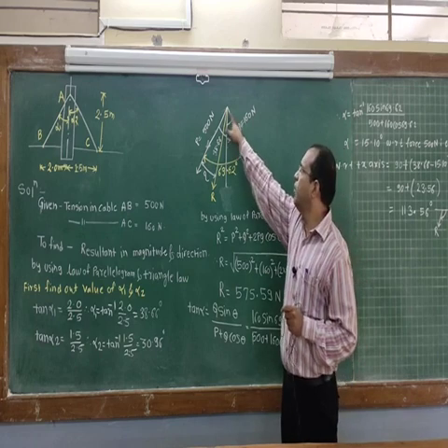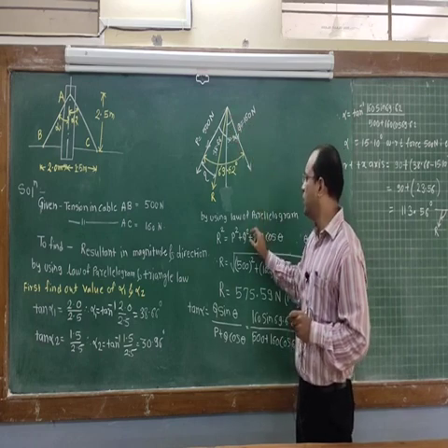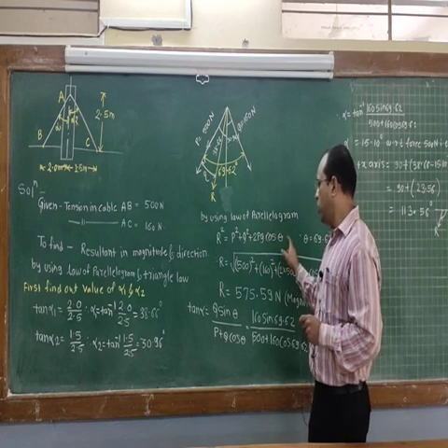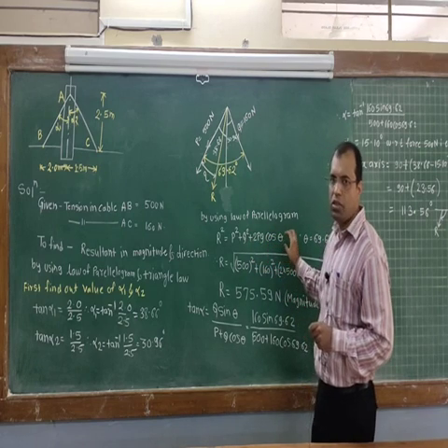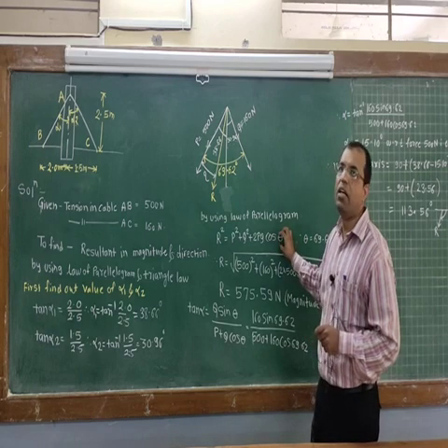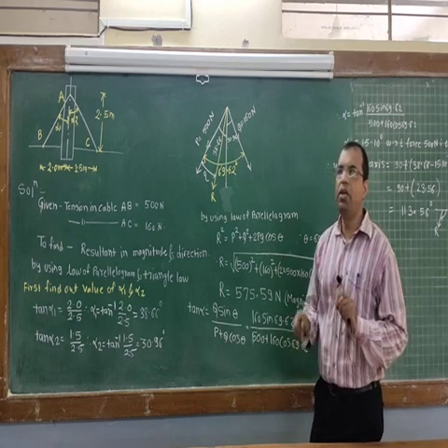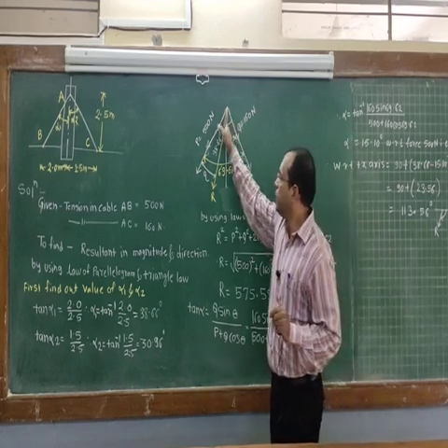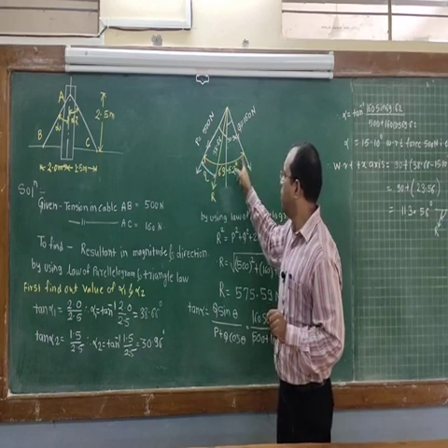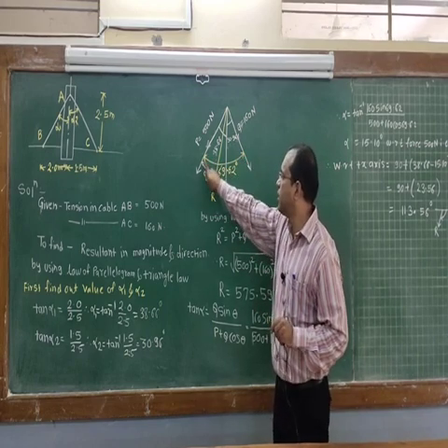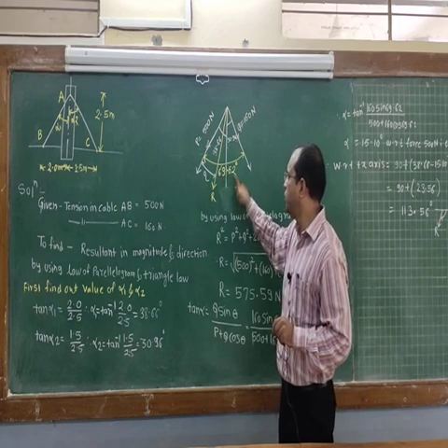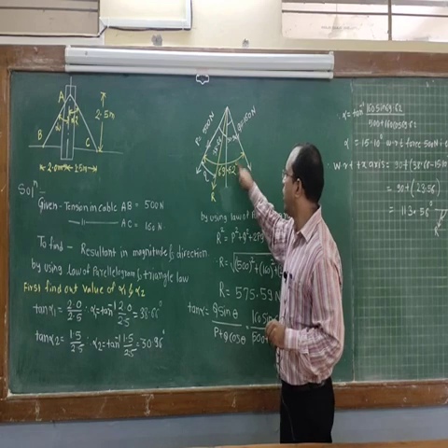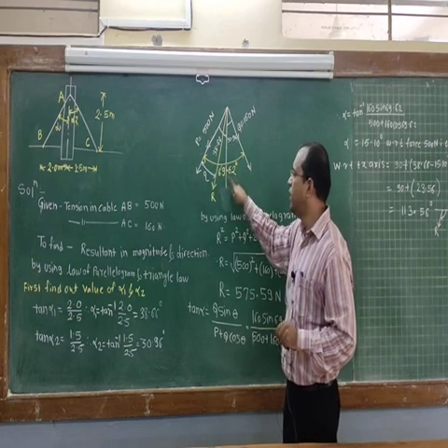Now the tension in the cable AC, let's say it is Q, that is 160 Newton, plus twice of PQ cos of theta. So please remember this theta. Many students make a mistake in that. Theta is the angle between the two cables or the two forces. So here theta is the angle made in between these two forces, the angle 69.62 between force P and force Q. This total included angle is 69.62, that is theta.